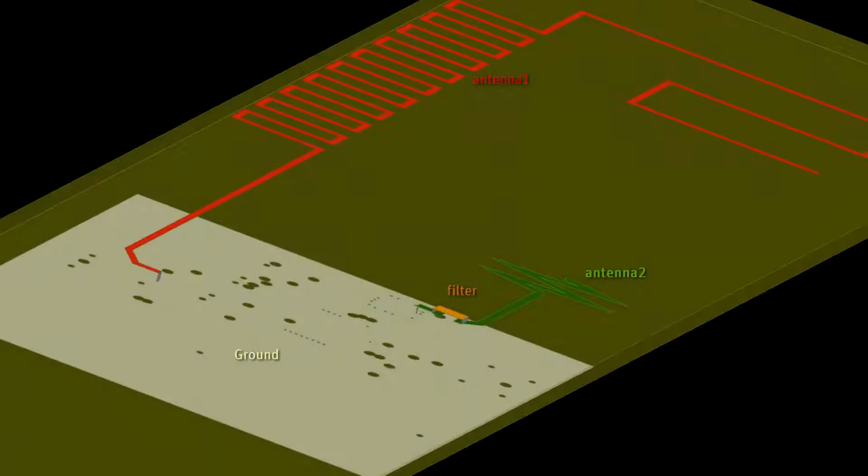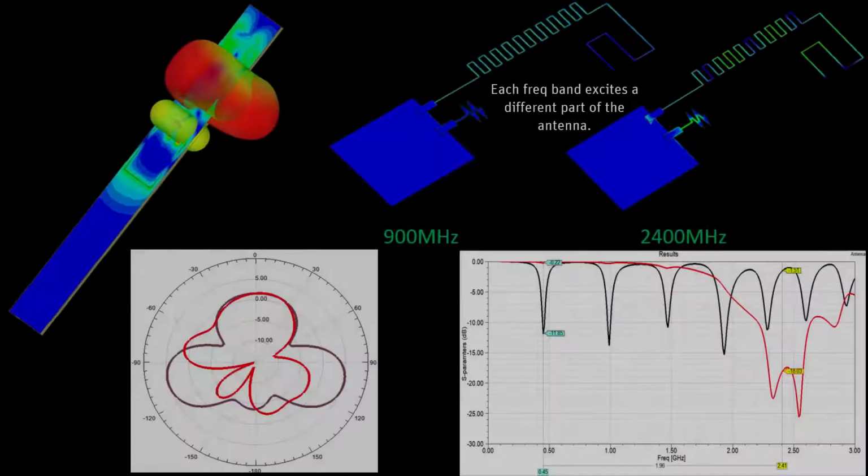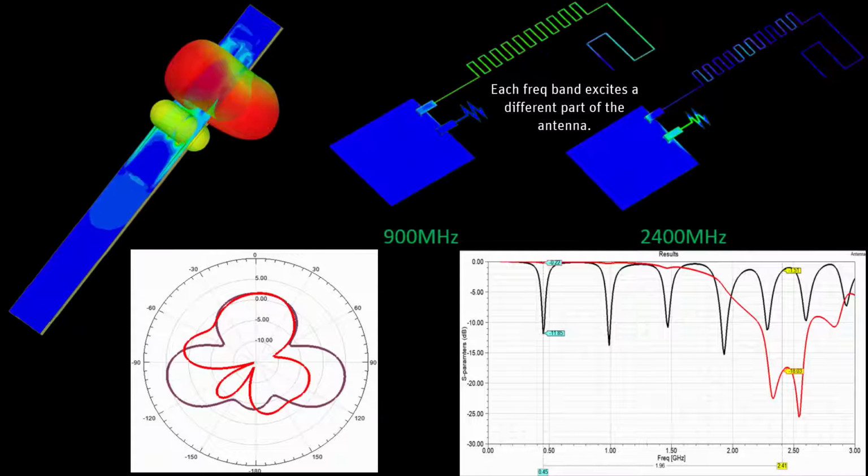A key element is wireless connectivity. Omnidirectional antennas can be created and solved using HFSS to predict their behavior in their operating environment. Solving the antenna in HFSS generates input impedance that will tell how well your antenna is matched to internal circuits. You can also view radiation patterns in both the near and far field.